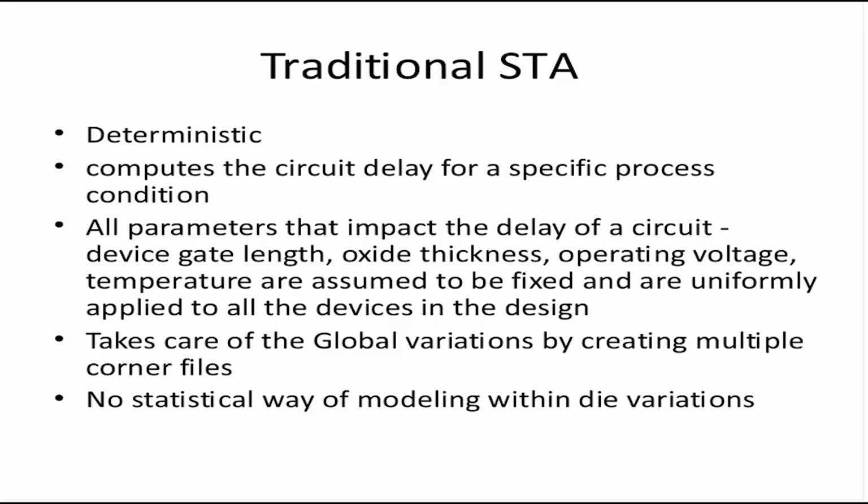What does it mean? It means that the physical effects are statistical in nature, but the modeling is not statistical. We are using a fixed guard band based technique to model the statistical physical delay. What is ideal?